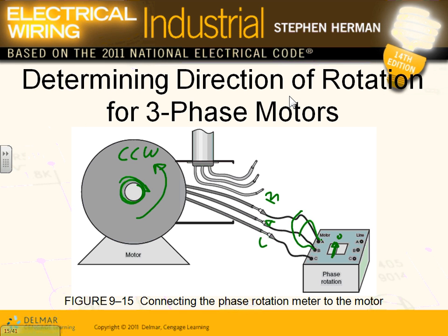Yeah, you had said that lowering the voltage decreases the current, yet by the formula, lowering the voltage would increase the current, which is why it would cook and smoke. I don't think you can have it both ways, can you? The formula that we had, lowering the voltage will increase the current. Yes. So by lowering the voltage, with the starter, you just got done telling us you put resistors in, lowering the voltage, and now you've just increased the current.